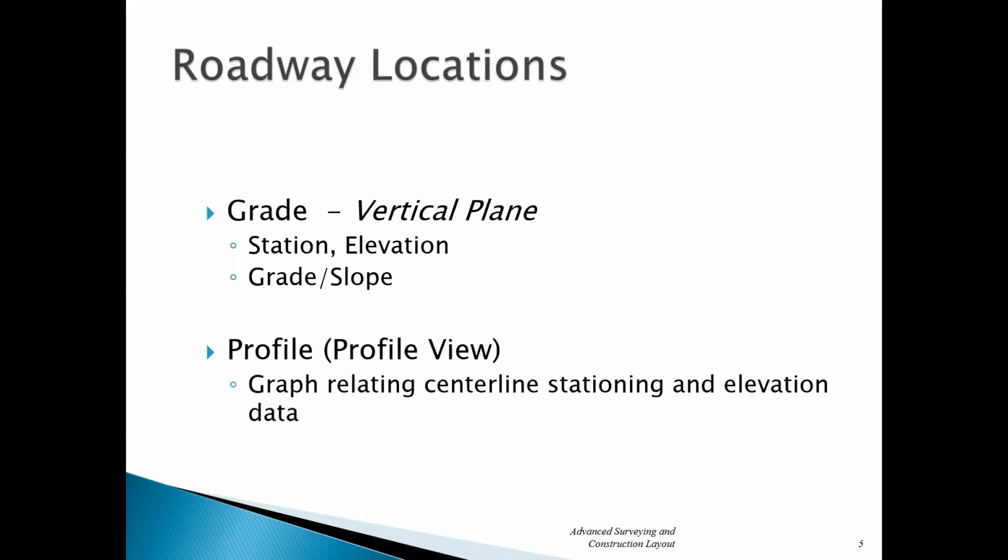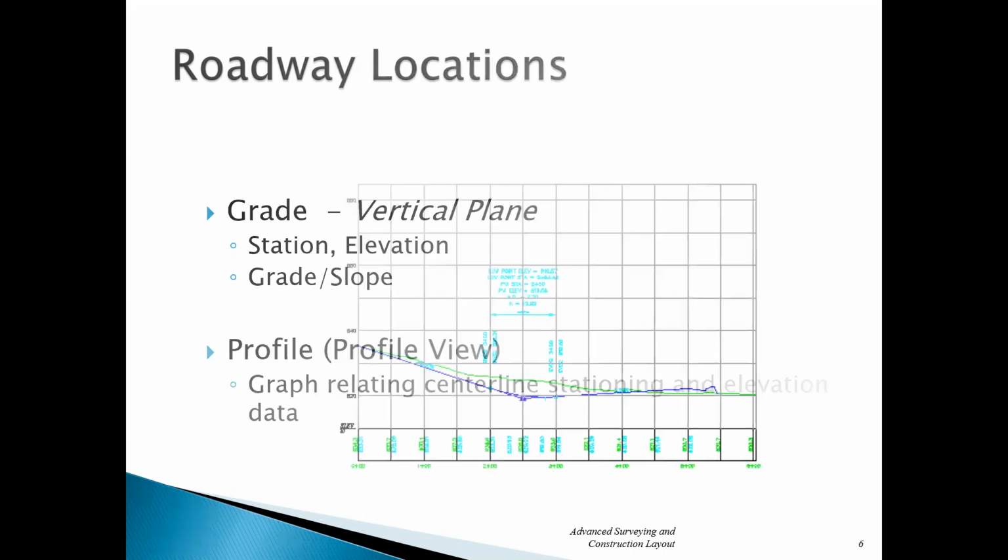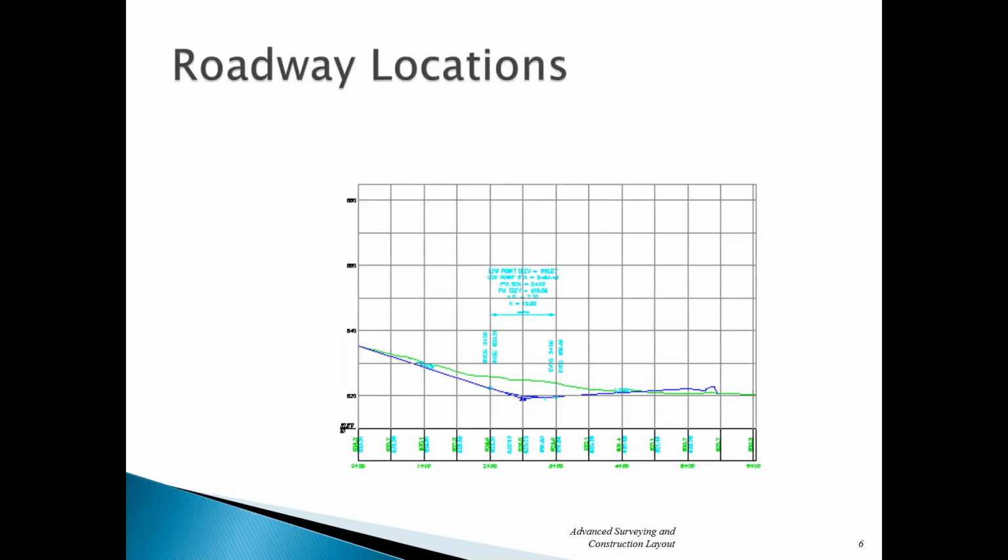So we did see this in terms of the sewers. We looked at profiles where we had the inverts and the slopes on the pipe and those kind of things. We've got the same stuff going on in a highway. It's just a lot more involved. So this would be a very simple example of a roadway profile. And at the bottom, those green numbers, those are your stations of that roadway. And again, that represents 100 horizontal feet from 1 plus 00 to 2 plus 00.